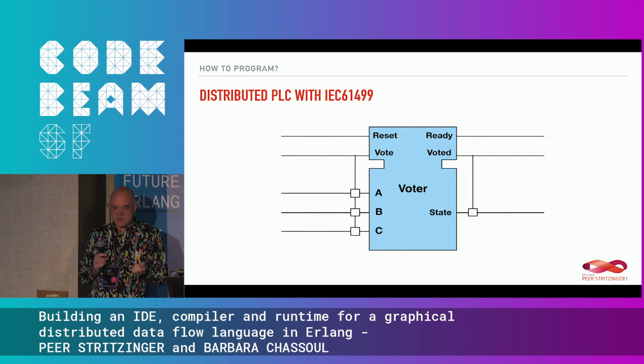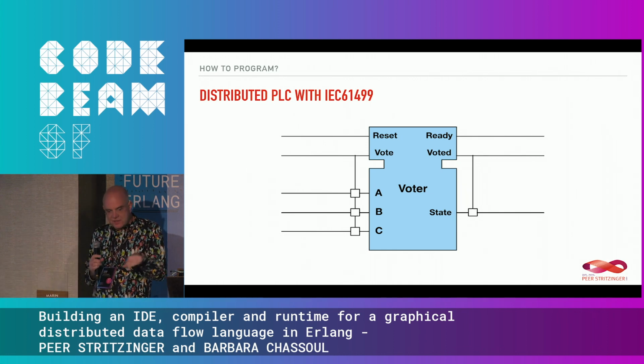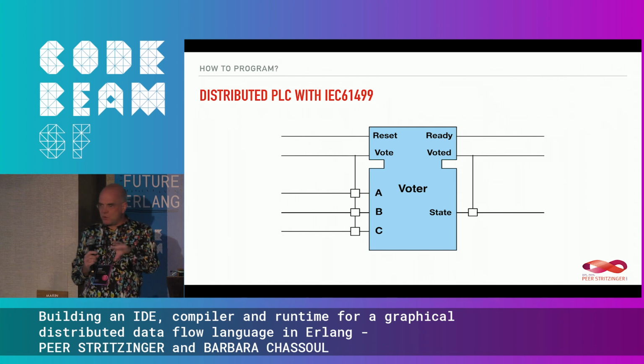So the standardization committee thought it would be cool that we don't run in cycles all the time, and we don't do synchronous data flow, but do asynchronous data flow. So everything is now modeled around events. That's the extra data they added. So it's still a function block. This box is a function block, implementing a function with state. And we see more of those later on.